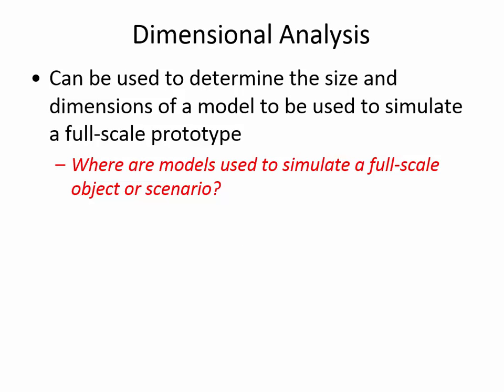Now, dimensional analysis is a way to recreate what's happening in the world with a smaller sized model. And the model is sometimes a physical model and sometimes it's a numerical model. But dimensional analysis will allow us to find out how the behavior of a small scale model can be applied to a larger size prototype. And why we have to be aware of that is because things that are small sometimes are unusually strong, for instance.